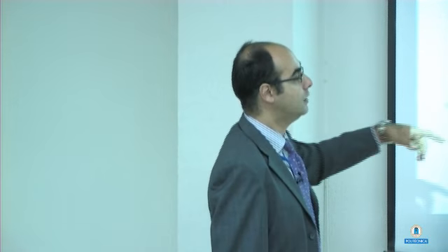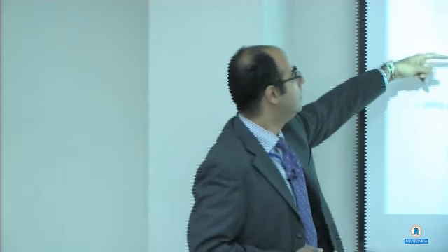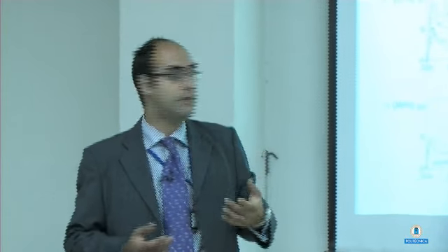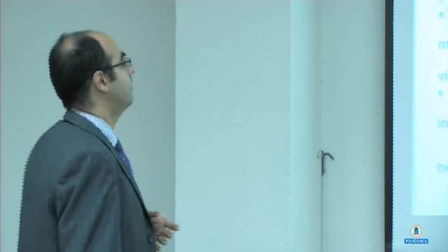This is a continuation of that investigation. This dealt with extracting some slab cores from the roof element and testing them in 4-point bending, and you can see here the huge dispersion of the results with vibrated concrete, while they were much more narrowly dispersed with self-consolidating concrete. And this could be beneficial also for the design, for the characteristic value and the safety factor that you have to employ.